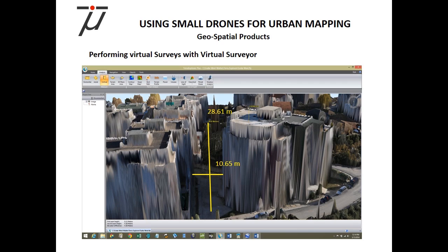Okay. So one of the biggest advantages of this idea is that you are forced through modeling in 3D. So you have everything in 3D, so you can survey it. You don't have to send a guy out there with a stick. If the area is visually accessible, it can be surveyed virtually. And that is really a big, big game changer, especially in areas where you still have to do cadastral surveying, where people have to establish their boundaries and so on.